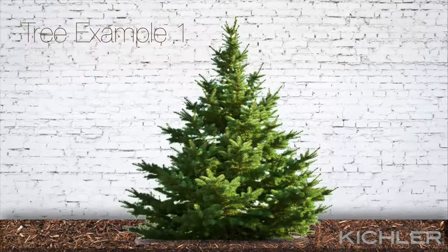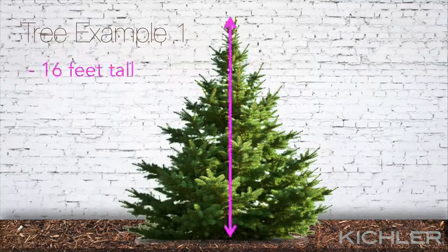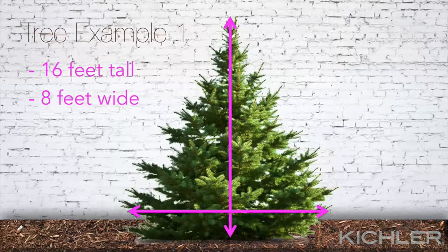One of the biggest mistakes first-time designers make is to underlight elements of the landscape. Trees almost always need 2 fixtures and a cross-lighting treatment. Let's consider a few examples to see how these considerations play out. First, suppose that we are going to light a coniferous tree that is 16 feet tall and has an 8-foot diameter at the base. What fixtures should we use to light this tree, and where should they be placed?